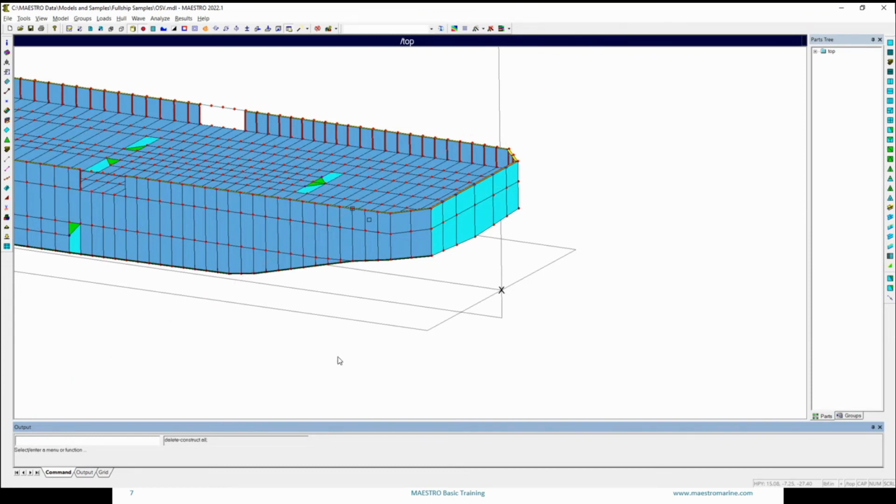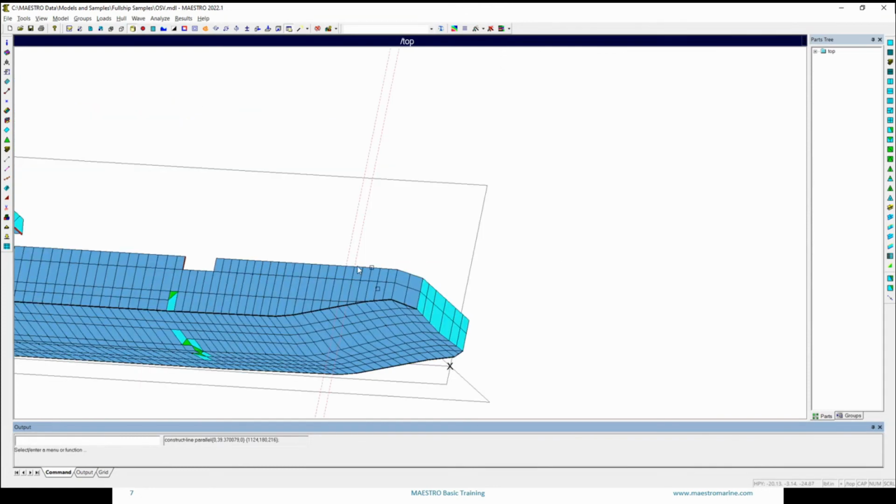So I'm going to delete all of these and afterwards. You do repeat afterwards. I'm sorry, I had it in the wrong order. You select the command, you say repeat, and then you can keep going. And now let's use the parallel command, and I'll put a line, let's see, it was still doing the repeat. Line parallel to this one, about that height.